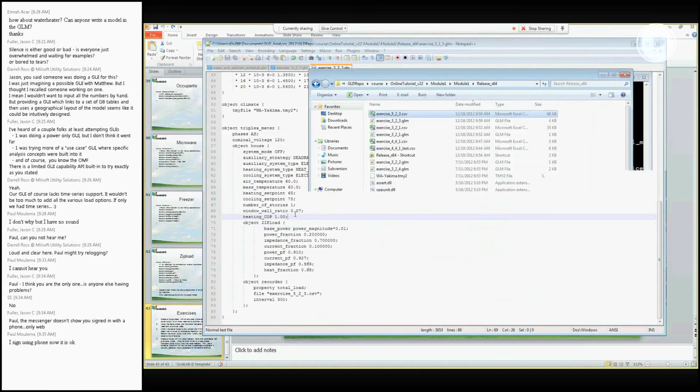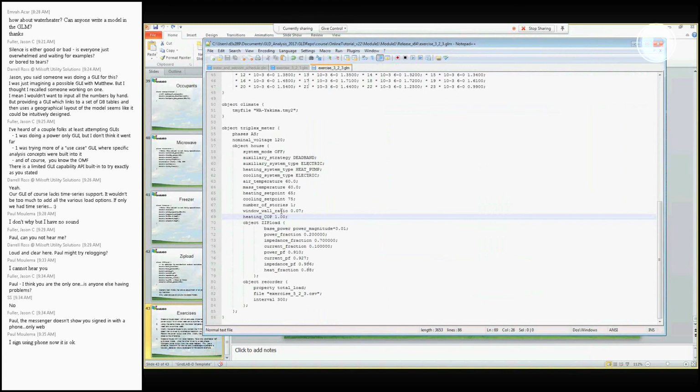But this ends up being a way that we represent a lot of our models. By just doing an HVAC system, just doing a zip load, and then the other piece that we'll typically add in there, and what I'm going to do here is, that heater is way too big for what I want to do here. So let's make this a much more reasonable efficiency.